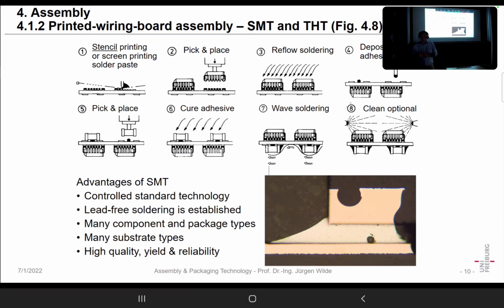So here in the image, it is screen printing, but normally, as we will see, it's mostly stencil printing. So we have a pattern of that paste. Typical value is somewhat below 100 micrometer of paste thickness. And that paste is wet and tacky.